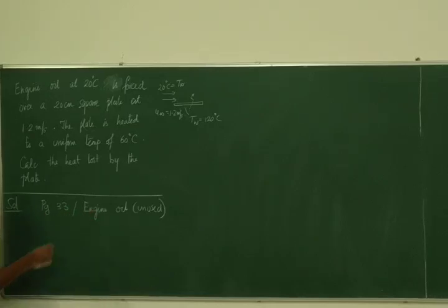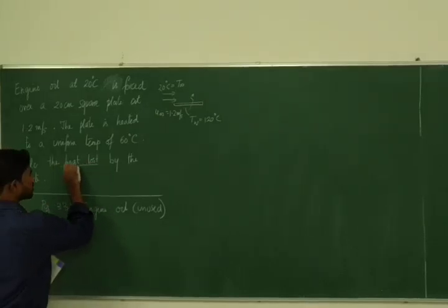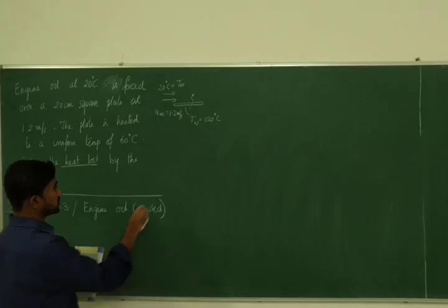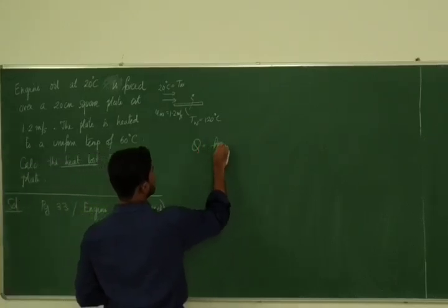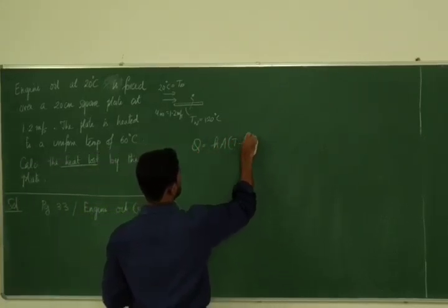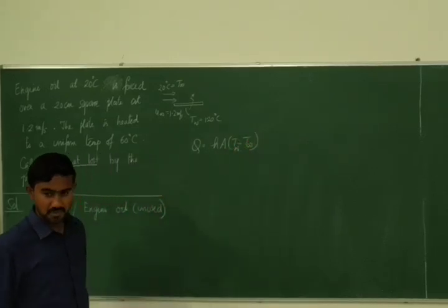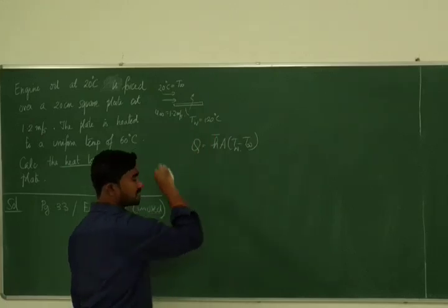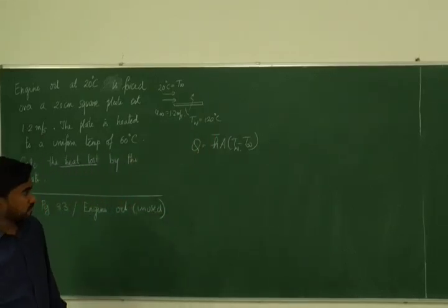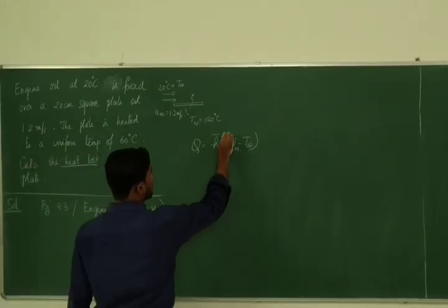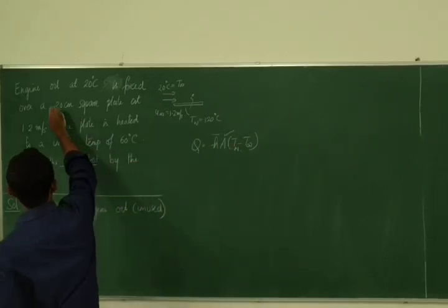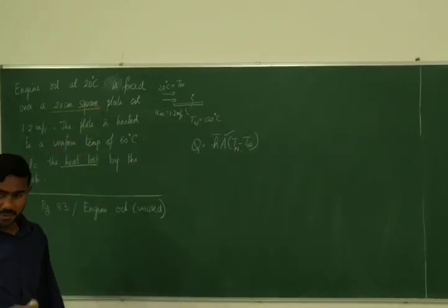Now we will take the properties of engine oil. First we have to take the Reynolds number. To find the heat transfer, how do you start thinking? To find the heat transfer, what do you use? Heat transfer, Newton's law of cooling, and you will use the average value of Nusselt number over the plate. Now, area is known. It's a 20 centimeter square plate, 20 by 20.